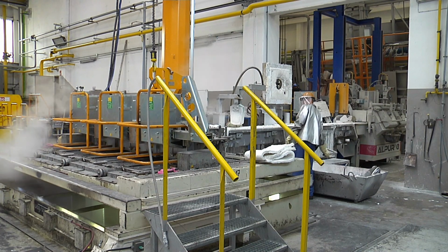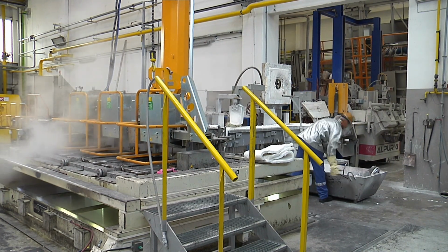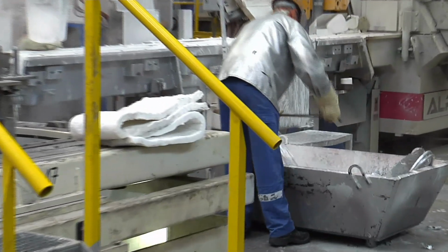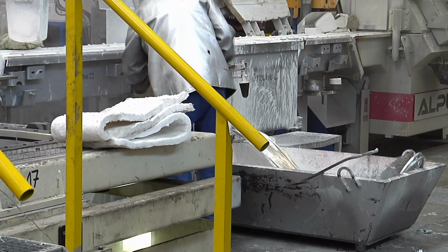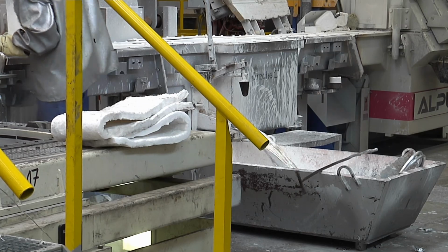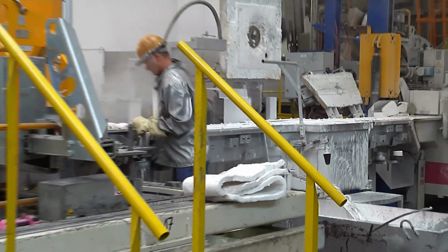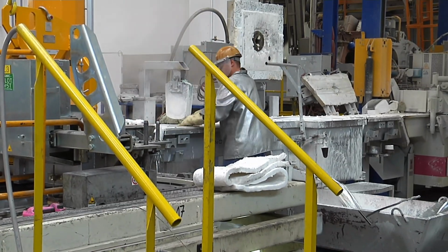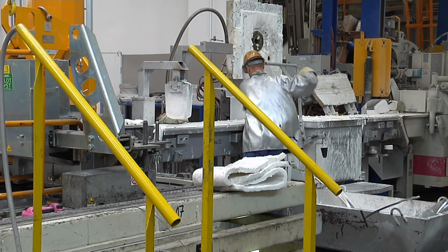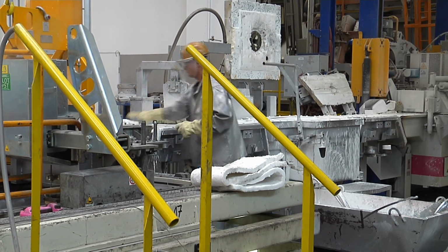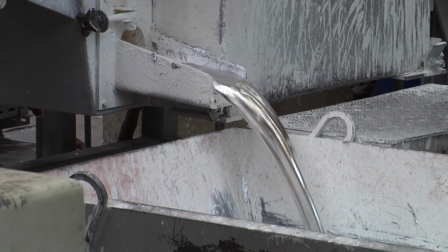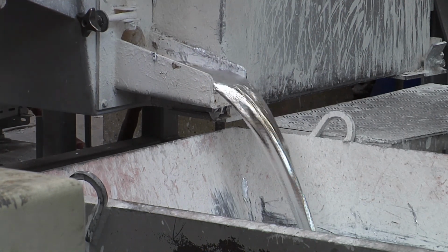Consumption of the metal present in the launder is awaited. As the metal falls into the launder, the filling PIDs tend to open the actuators wide. When the metal is almost finished, the level in the slabs decreases. Once the threshold has been reached, the regulated down request stops, the platform stops, and the cast, from the point of view of the ALMEC board, is considered closed. Final cooling will activate on the control panel to effectively close the cast.